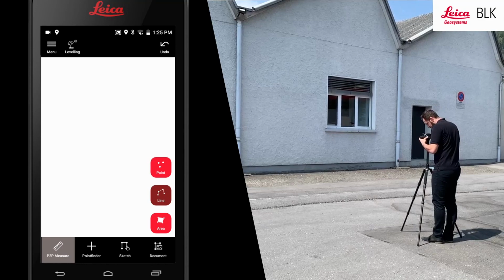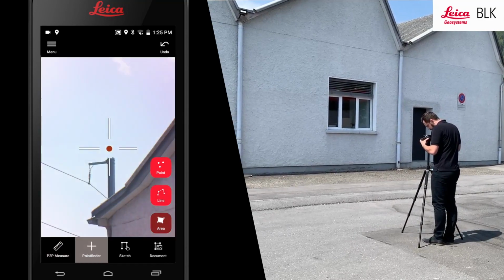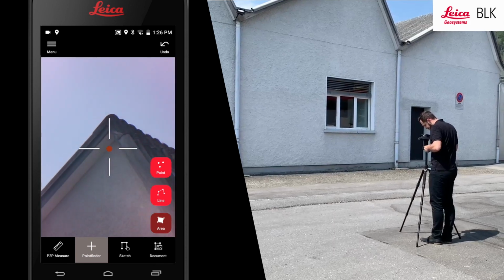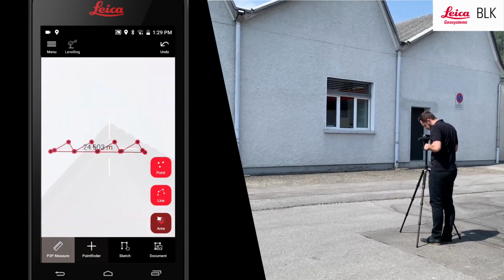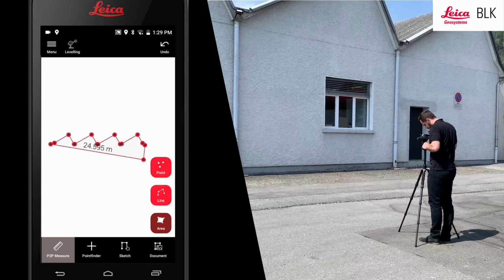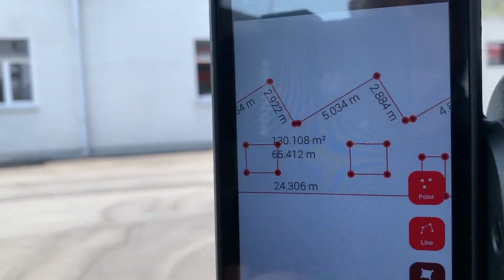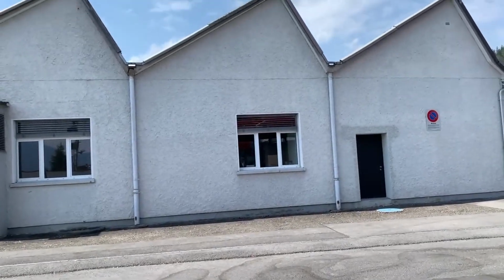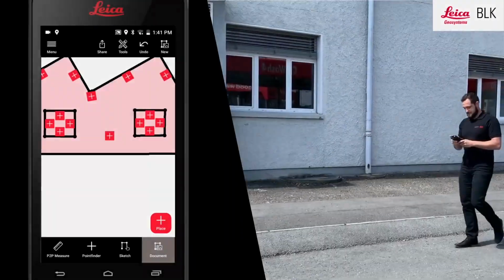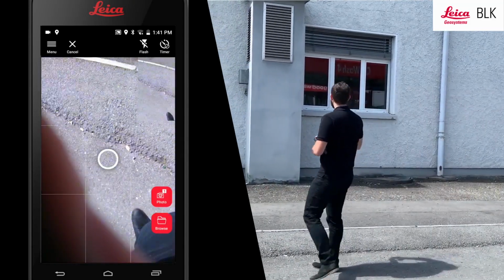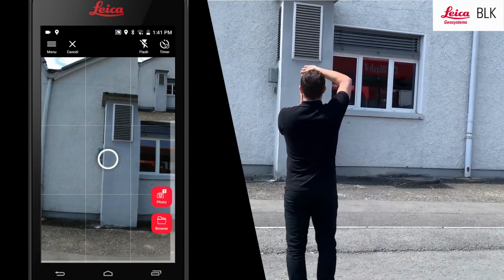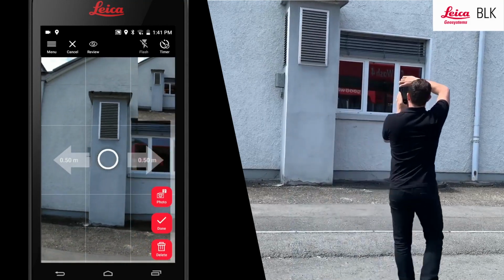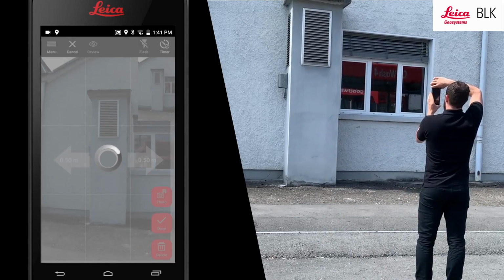And you're ready to document. You can switch between area, line and point to define any aspect of your facade. Direct the laser to your target and measure. On the screen, your facade will be drawn out. With the drawing being displayed before you, you can easily see what was already measured and where we are still missing dimensions. Now comes the best part, since on this layout we can attach measurable 3D images. This way, we will never forget any measurements and will avoid guessing distances or returning to the site to remeasure.